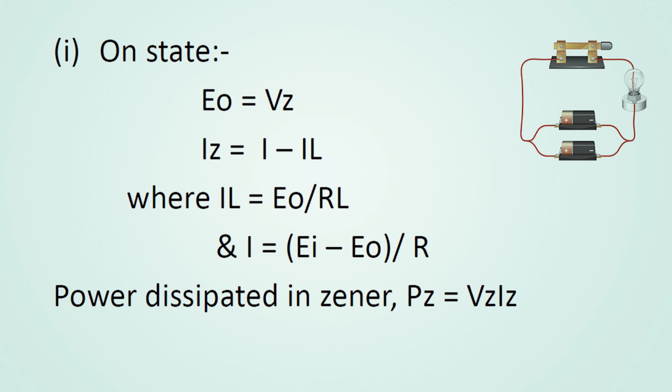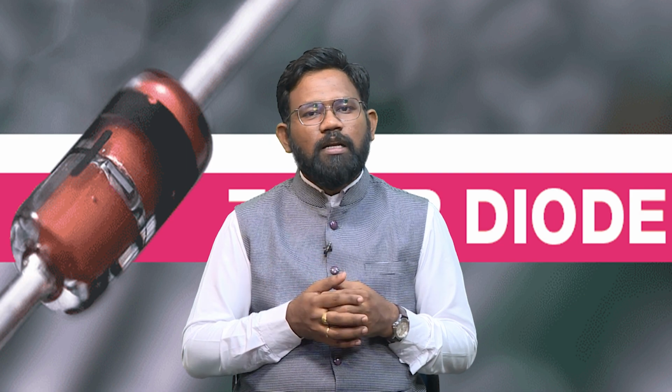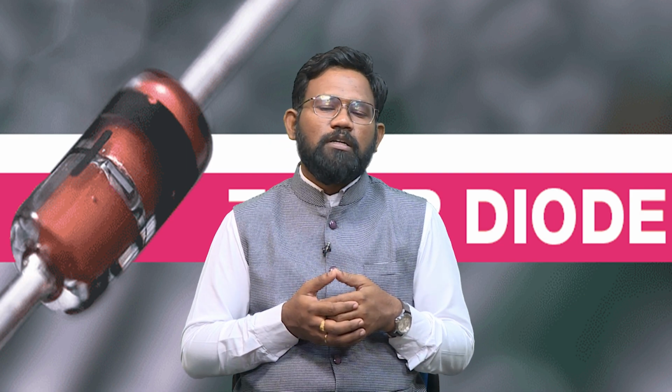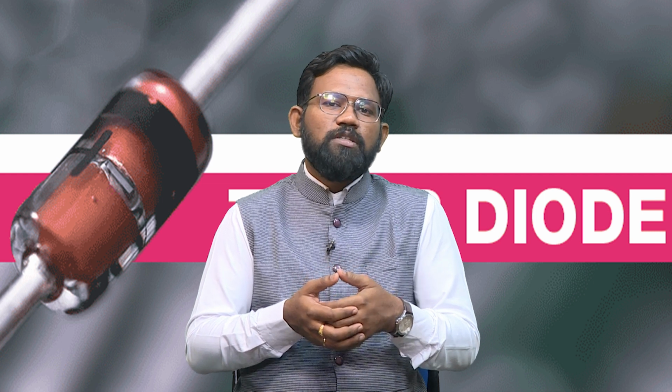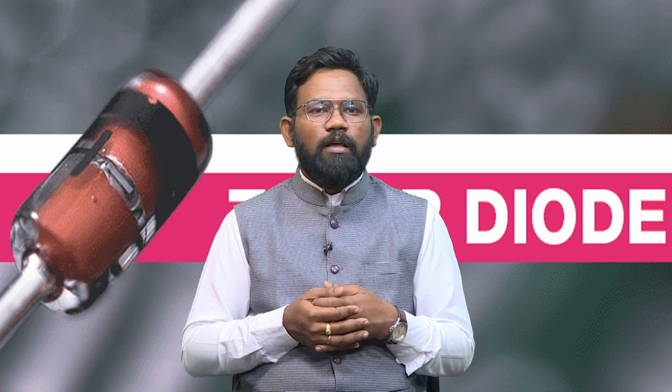From this we can calculate the power dissipated in the Zener diode, denoted by PZ, and its value comes out to be VZ into IZ. So, the power dissipated in the Zener diode when it is in on state is equal to VZ into IZ, where IZ is equal to I minus IL.